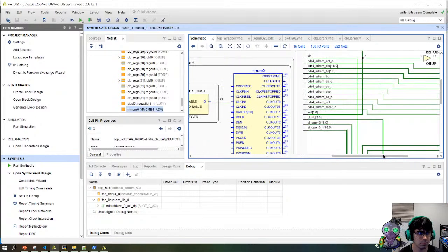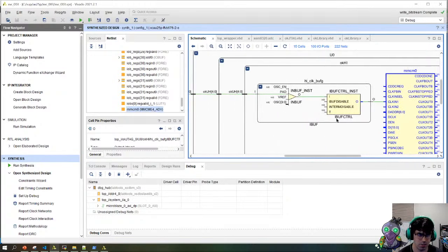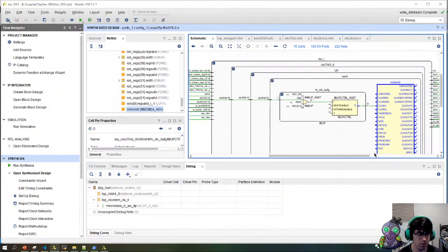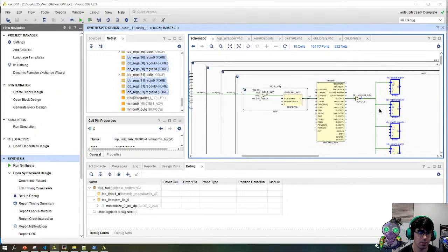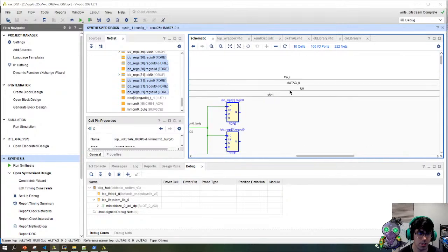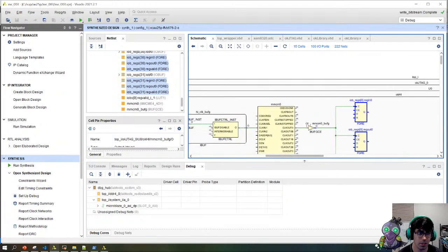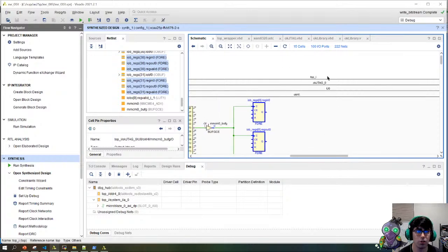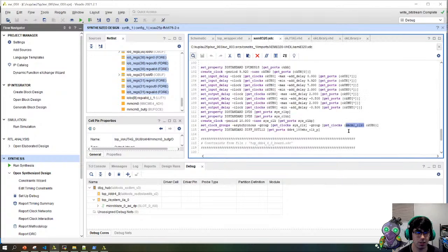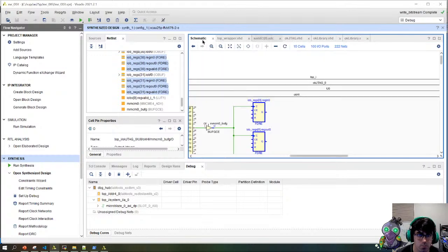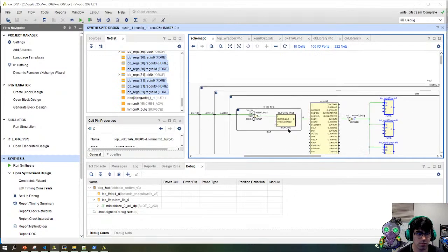Lock in. There is no buffer here. Lockout. That's a BUFG. That's instantiated in the okHI, which is inside U0. So where is okHI? Cool. So that should be done at the Verilog level. I think we just need to put that constraint in there. We'll see how it goes. But yeah, it looks fine.